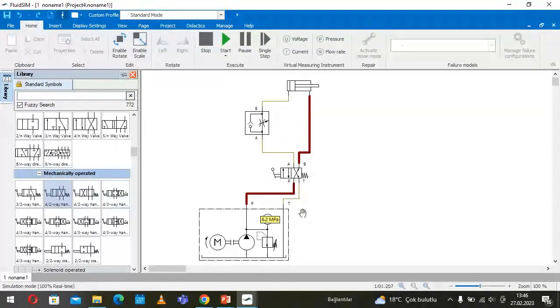Okay. And mainly we use the flow control for the advanced stroke, because in most applications the piston executes the work in advanced stroke, and therefore, during the execution of the work, the speed has to be adjustable.